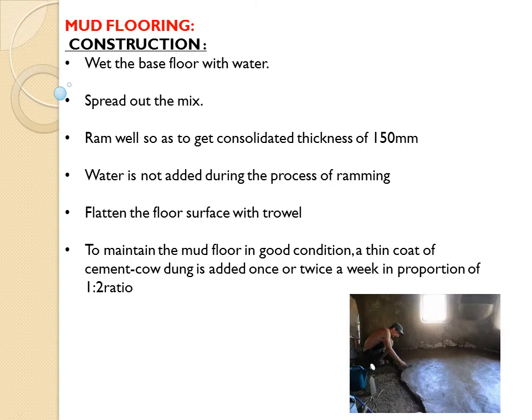In the same way, to maintain the mud flooring in good condition, a thin coat of cement and cow dung is added once or twice a week in a proportion of 1:2. So whatever flooring is done, the way we do tiling, once the base is ready, we put tiles, then again a cement mortar fixture for properly fixing it. In the same way, to maintain the mud flooring, as it's mud,